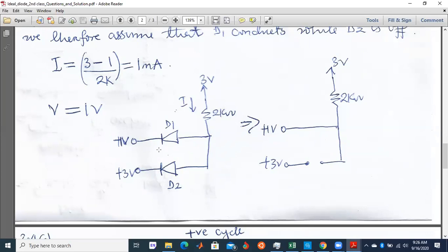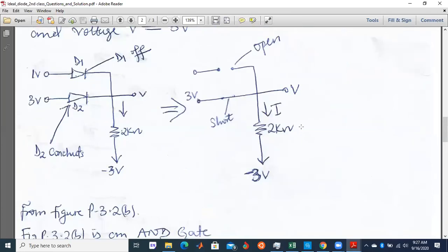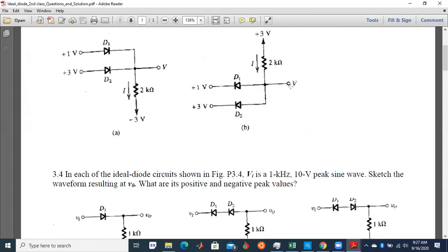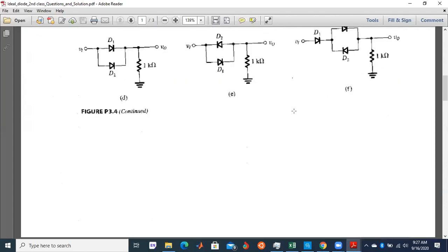So it is the diode that will be on. So it will be replaced by wire. So this is the diode replaced by wire. And the output voltage is attached here. The output voltage is here. So it means that this one will be replaced by wire, and the value of voltage here, 1 volt, will be fed here. Oh, okay. Clear, okay, alhamdulillah.